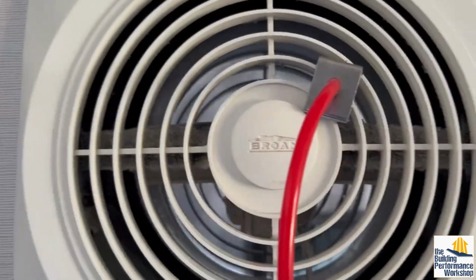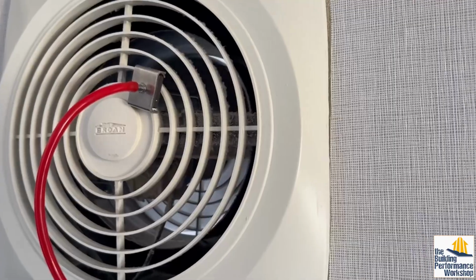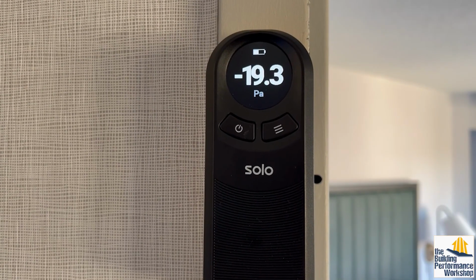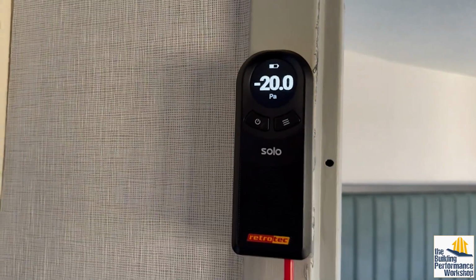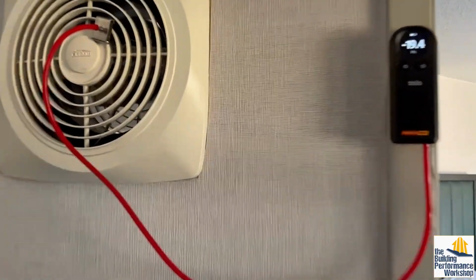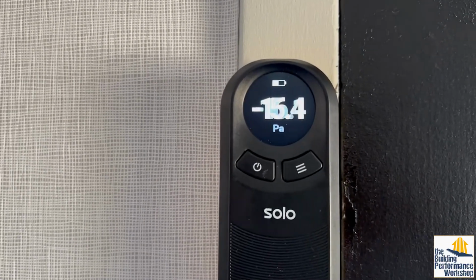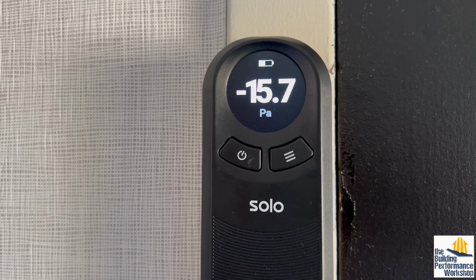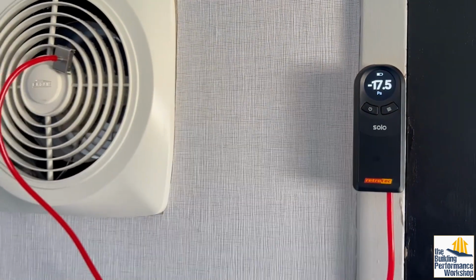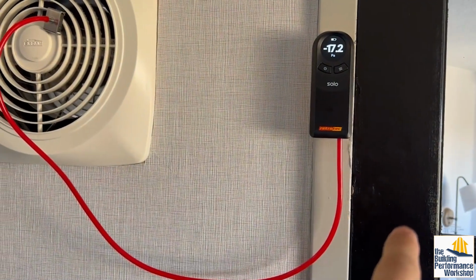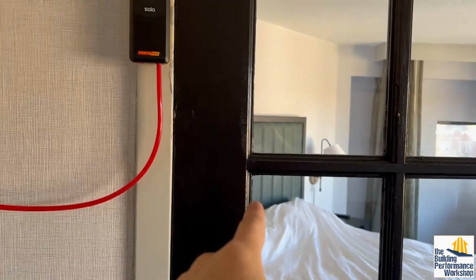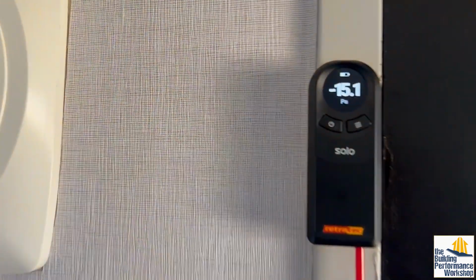And now what we can do is simply check ourselves, yeah, 0. And now that we're running, we've got the pressure reading in there, 19 pascals. Now, does the pressure change when we close the door? That's an interesting question. Oh, interesting. So we can drop the airflow if we close that door. Now, before we start investigating the pressure that's going on in that room that might be causing that, let's see what we got going on.